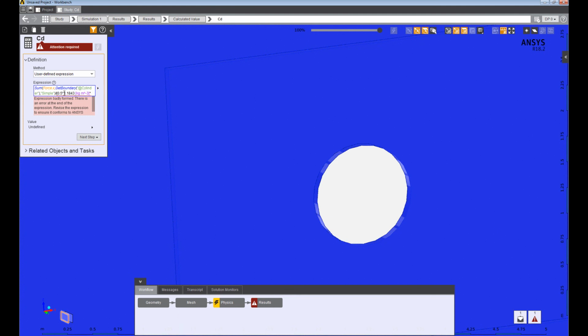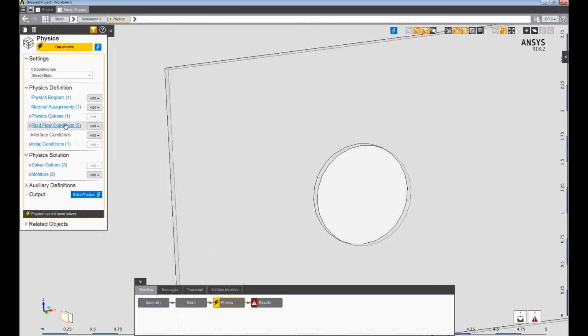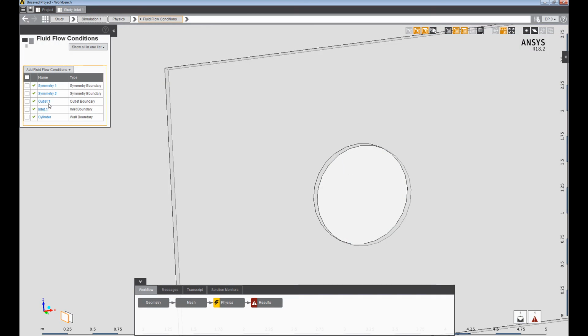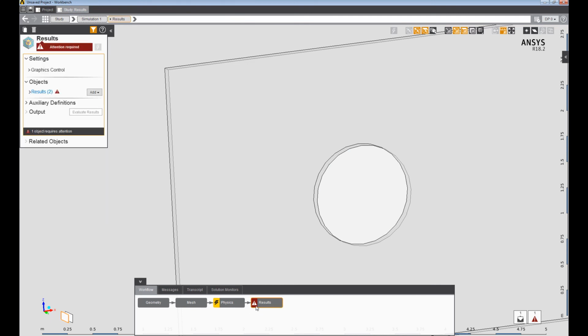So the inlet velocity is, let's say, the average of velocity in the x direction. Get the boundary at, in brackets, inlet 1, and we'll also do a simple average here because it should be at the same value. Let's see if that works. So quick check of my names. So this is indeed called inlet 1.